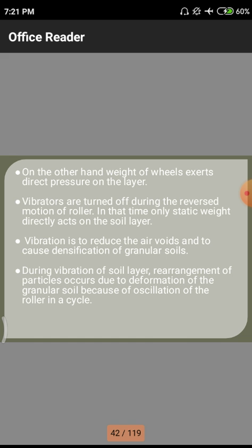Particle sizes normally vary from 5 mm to 10 mm. That means there may be a huge amount of voids lying between those particles, so we need to avoid those voids by using this vibratory and rolling mechanism.